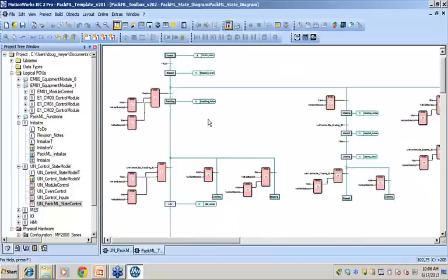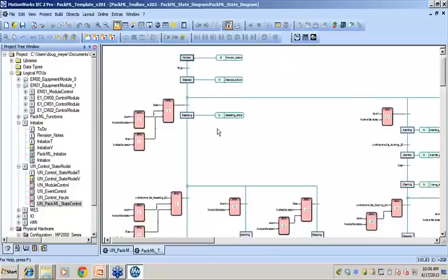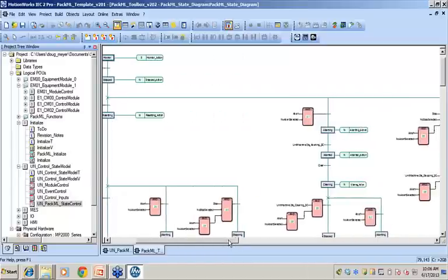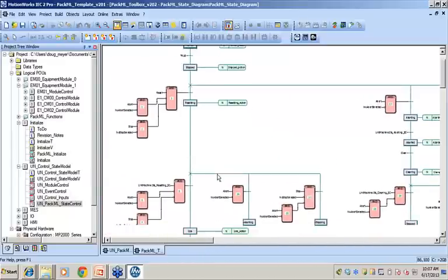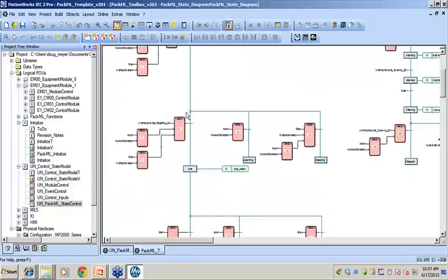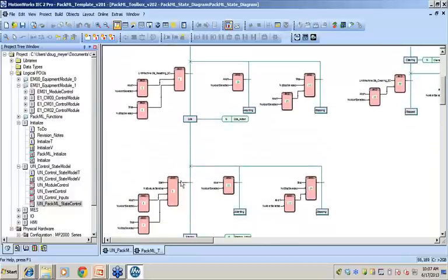We start in a stop state, and then depending which transition you get, you can go to the resetting state, the aborting state, or the stopping state. If you get the reset command, you go to idle. If you get the start command, you go to starting. At any one of these, you can go to the aborting or the stopping state.